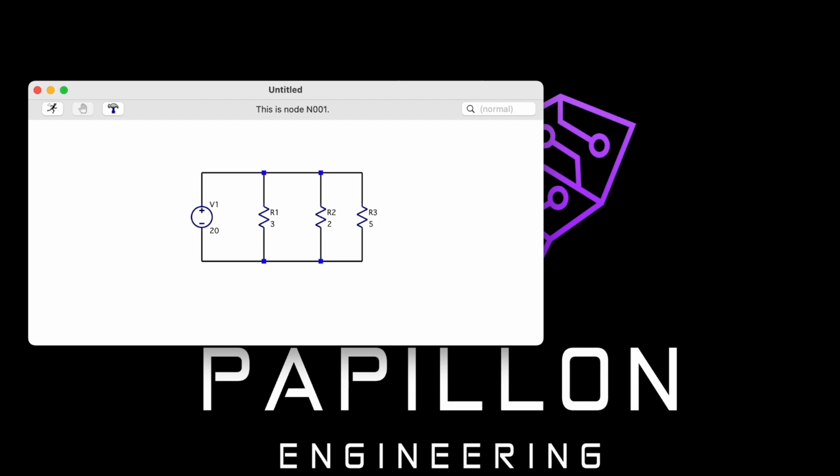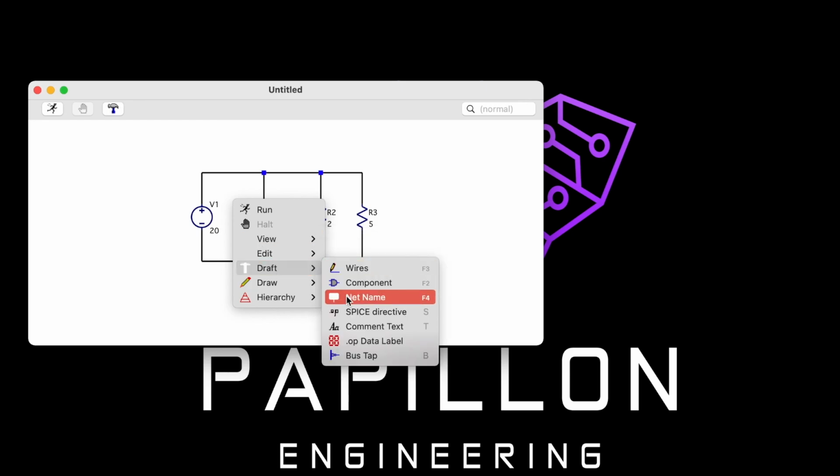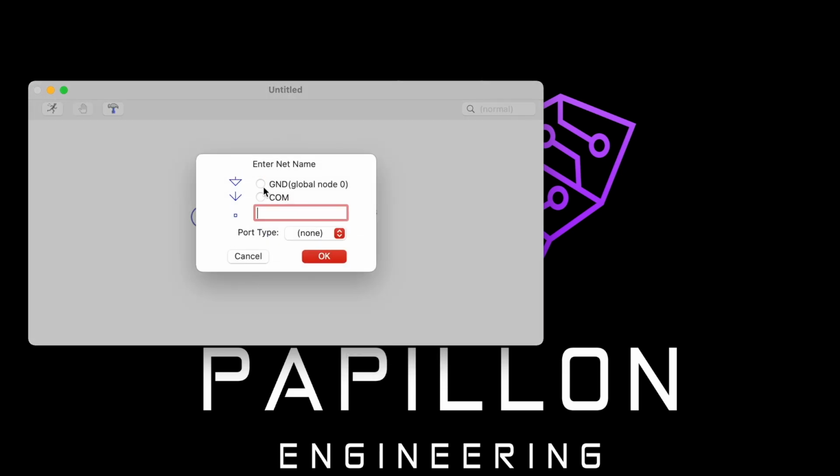And if you're new to circuits, or you have a little bit of background, you should hopefully realize that anytime you have resistors that are in parallel with each other, they all just share the same voltages. So if we have 20 volts as our source, hopefully we're going to read 20 volts across each of the resistors. So their voltages should be the same.